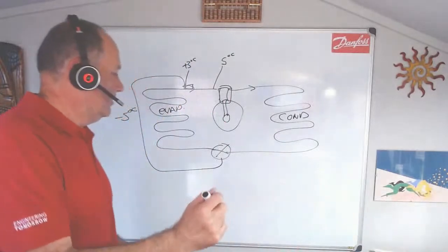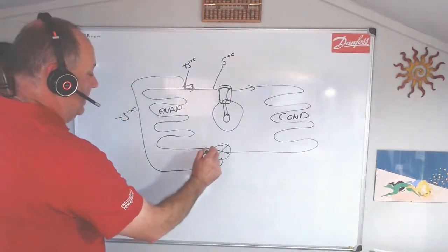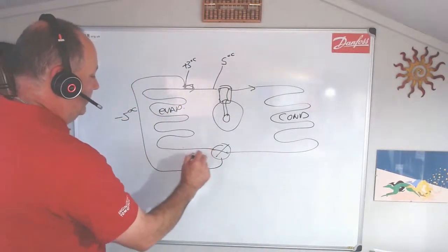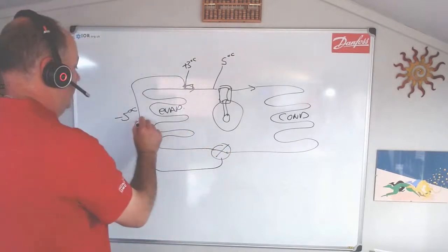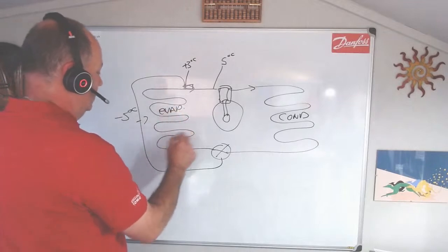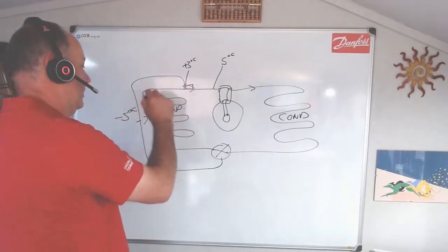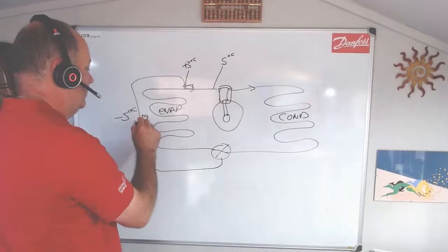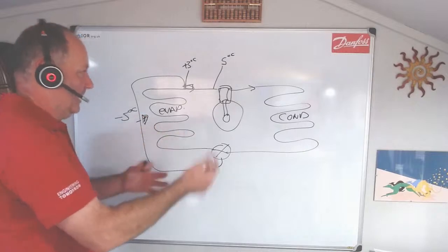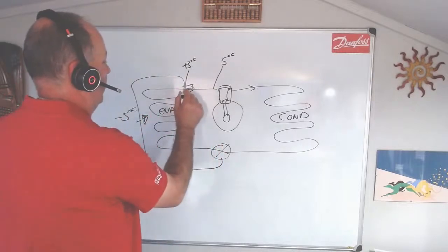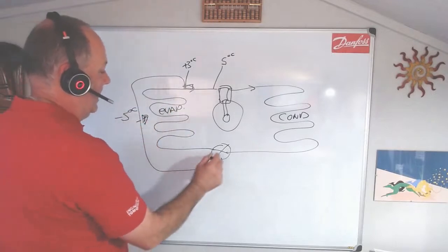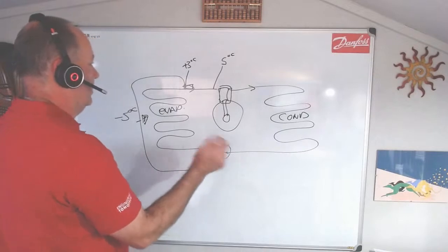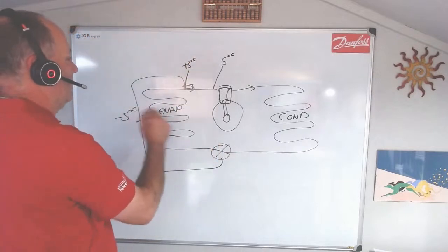We feed our liquid into our evaporator through the expansion valve, and we pass air over that evaporator. The refrigerant that's boiling off in our evaporator is absorbing our heat. So think of that like the kettle. Out of our evaporator, we don't want -5, because we'd have a liquid vapor mix, which we don't want. So we've got +3, we've got 7K superheat.